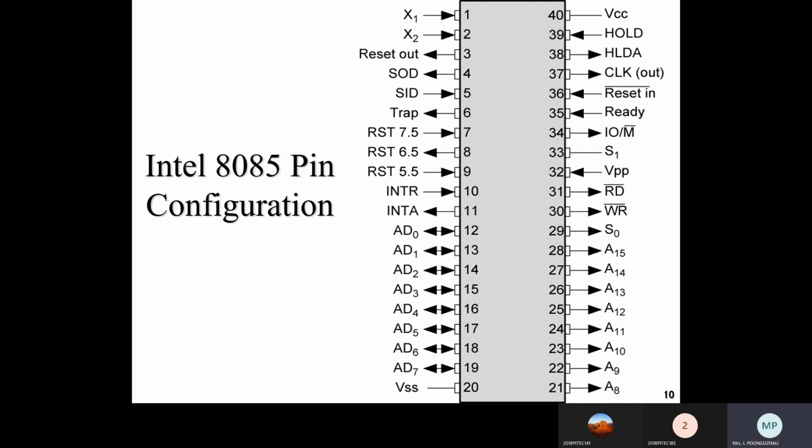In general, the processor will be executing a sequence of instructions. If there is something urgent we want to do, for example, when the processor is doing its work and we move our cursor with the mouse, or when we type a key on the keyboard, that has to be displayed, right? So these interrupt lines are connected to the keyboard or to the mouse. These IO devices are connected to the interrupt lines. That means when a key is pressed, it has to be displayed. So the general sequence has to be stopped and it has to respond.